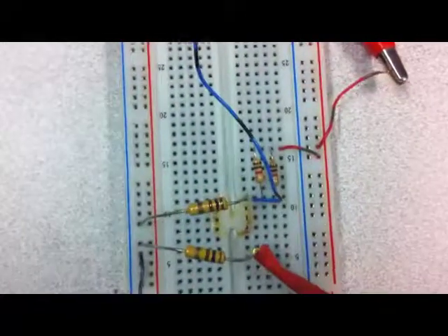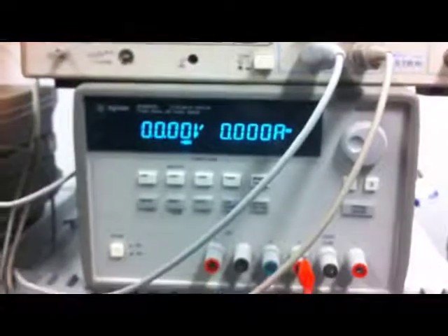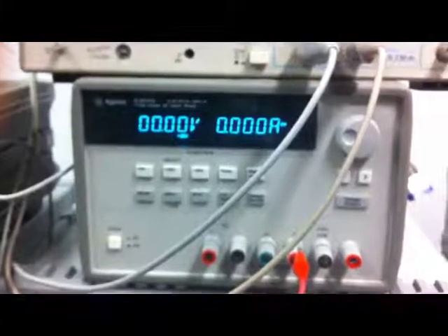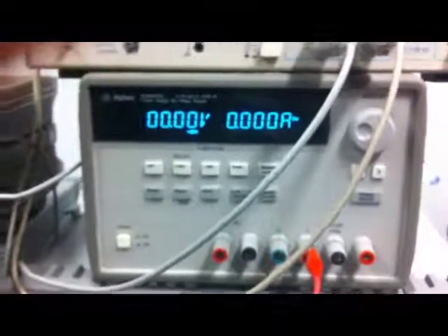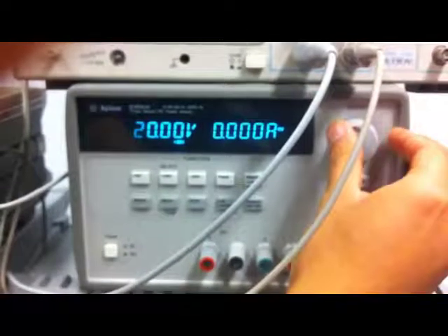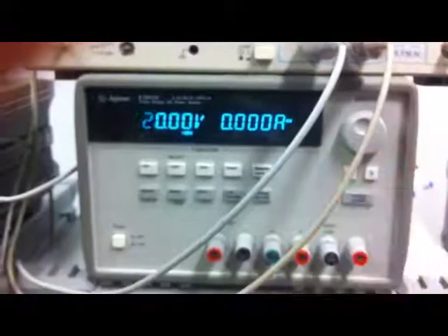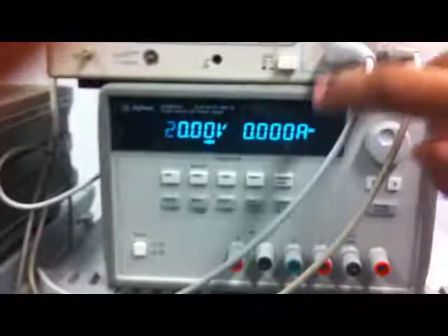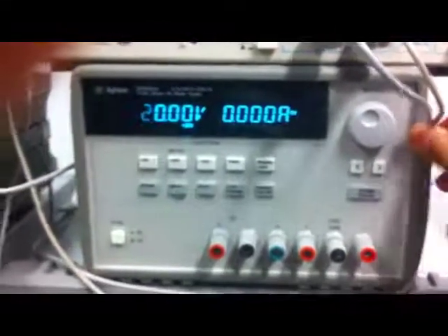And we're going to show you how to set that up, but first let's look at the power supply and how to set up a power supply. So first of all, make sure your power supply is not connected to your circuit when you're changing the settings, or make sure the output is off. For the purpose of this lab, we're going to set the power supply to 20 volts, and we're currently on the voltage setting, but we want to limit our current to make a workaround for a current supply, because we don't have that in this lab.